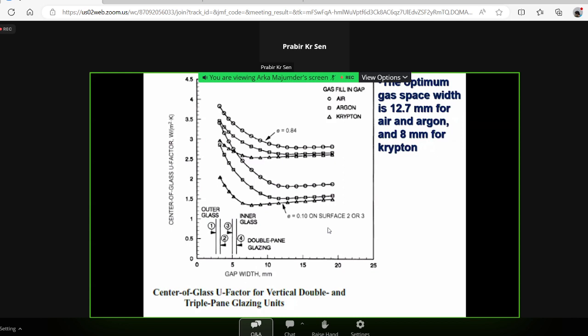But if you use low emissivity glass, and there is low emissivity glass that is also very common in this country, we'll have to go to the next three curves. There, with an air gap in between, with low emissivity glass, you can see everything outside from inside. But from outside, you cannot see much of the inside of the building. So with an air gap inside, the U factor will be even less than 2. Next.